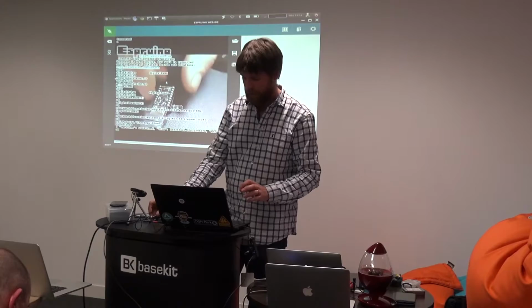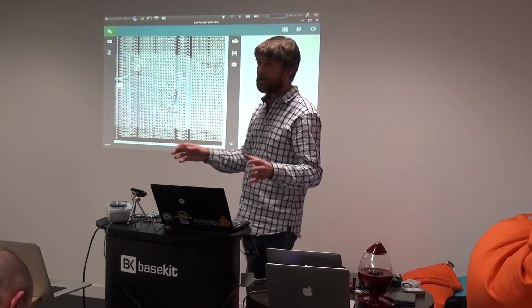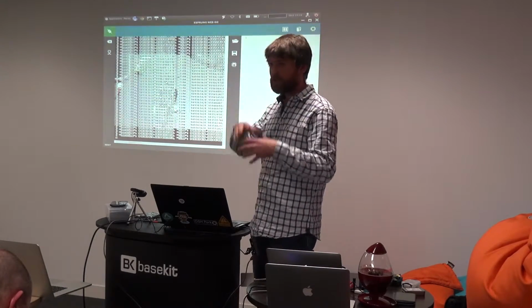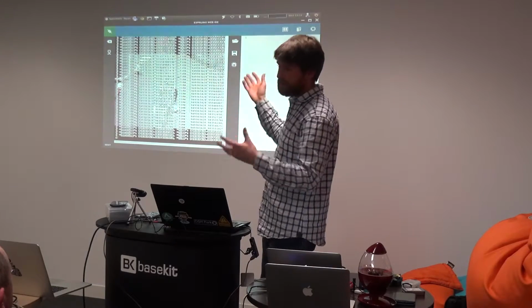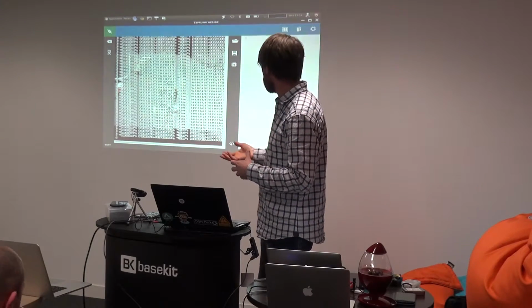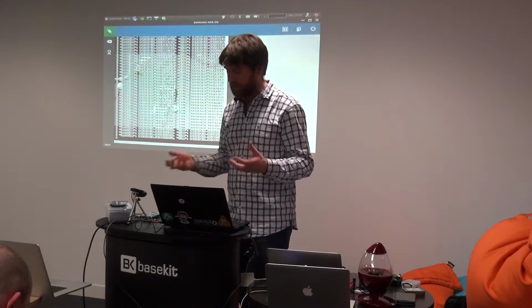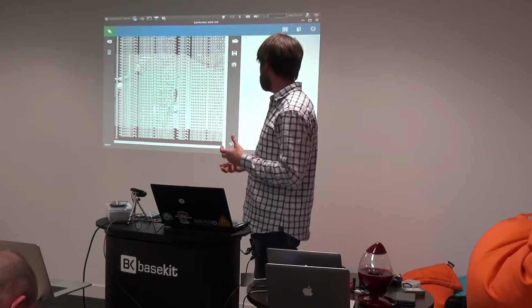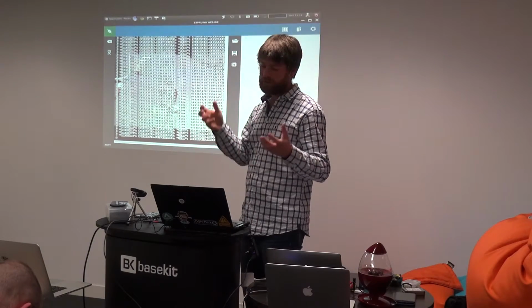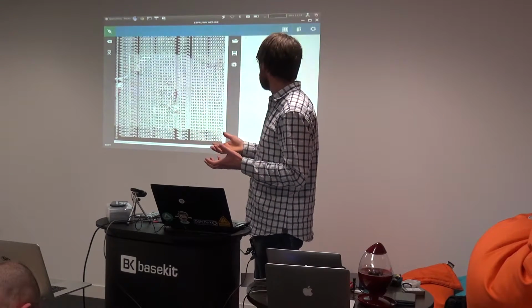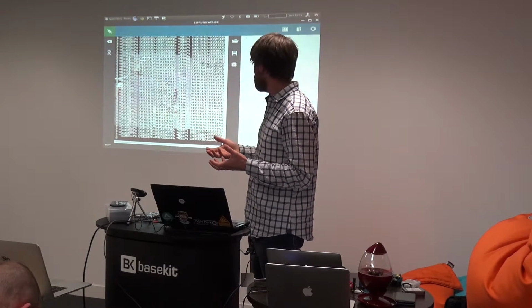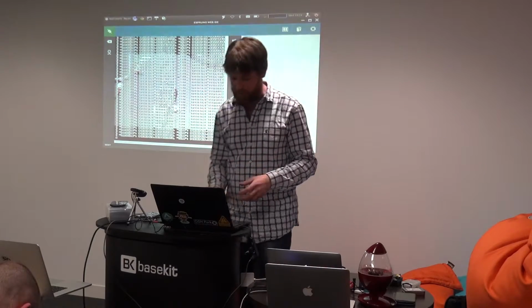And now, if I move this, you'll see that a massive amount of events come in, which are basically this spring moving around and hitting and moving away from the little contact inside it. So, if we want to do this light that turns on and turns off, all we want to do is react to the very first event, and ignore all the rest of them.